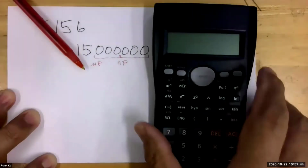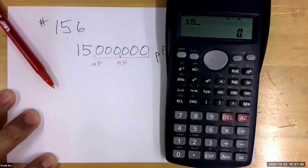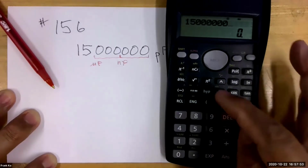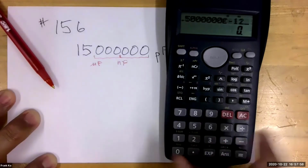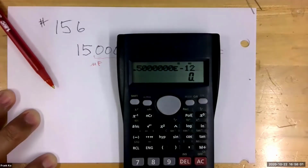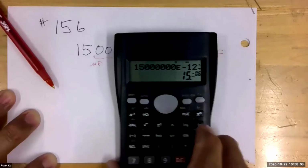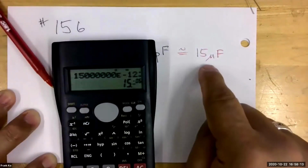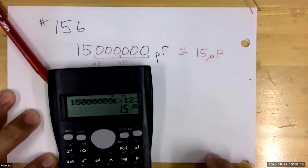If I could do this on the calculator, you can also do this on your calculator. Key in 1, 5 and enter your 1, 2, 3, 4, 5, 6 zeros. And then remember, exponent -12. Yes, there's mine. And they hit equals. And it's non-engineering. So what do I need to do? I hit engineering. And what do I have? 15 microfarads. So did my calculator give us 15, and did my moving of the decimal point every 3 places also give us 15 microfarads?